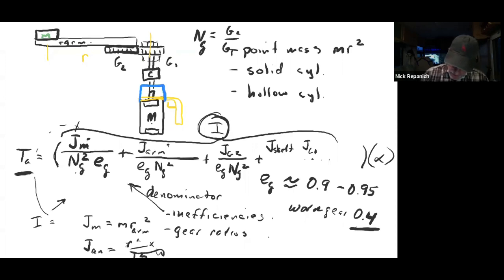You would do a gear head. That would be preferable. And the reason you would do a gear head is that a gear head, you buy it, has predictable tolerances, predictable stiffness, predictable backlash. The manufacturer gives you those things, but it's a series of gears, and the first gear that's on the motor is tiny. And everything after that, all those other gear passes in order to get to a 50-to-1 gear